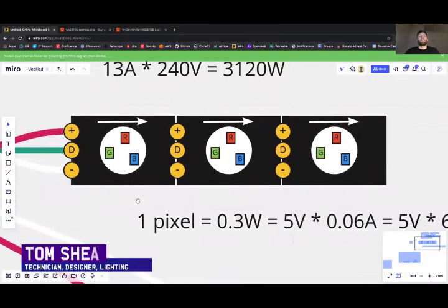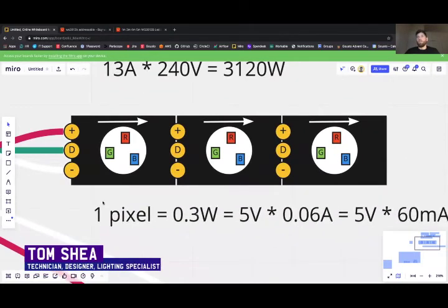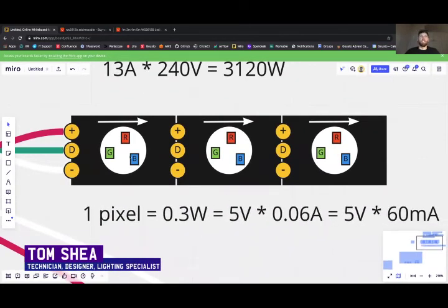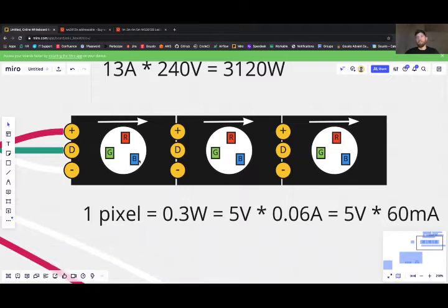So if we know that driving more current into each of these channels in the emitter makes them brighter, and we also know that white requires an equivalent contribution from each of the channels, then we can infer that the brightest this emitter can ever get is when all 3 of the channels are set to their maximum brightnesses, and the color that it will look like is white.